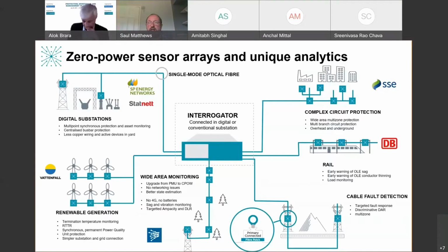And so monitoring electrical stress, sheath current monitoring, looking for signs of overheating, ohmic overheating at the terminations, all of these devices are built into one system to instrument the wind farm and provide earlier warnings of failures of critical equipment. And of course, a failure in offshore wind, you can probably imagine, costs millions and months of outage and campaign costs to replace these cables.